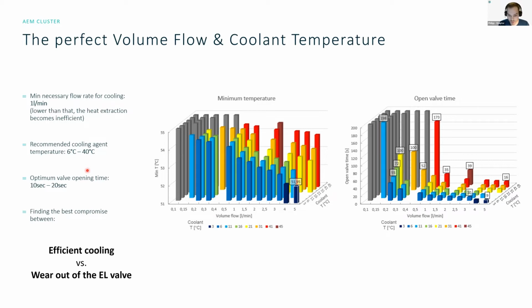And what I also want to show here is we need to find a balance between efficient cooling and wear out of the electrolyzer valve, because the more often we close and open the valve, of course, the quicker it wears out. On the other hand, we want sufficient cooling and we want to build up this cooling cycle in an efficient way, which also considers pumps and all the other devices that we're now taking a look at.